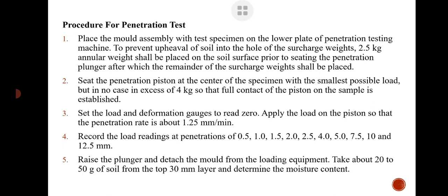For the soaking in water for 96 hours. Before soaking, you make sure that the test specimen is covered with a filter paper at the top and at the bottom, because any inert material should not penetrate into the surface of that mold.